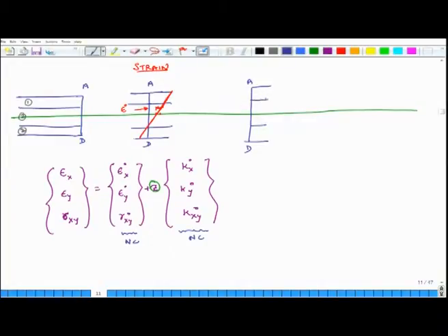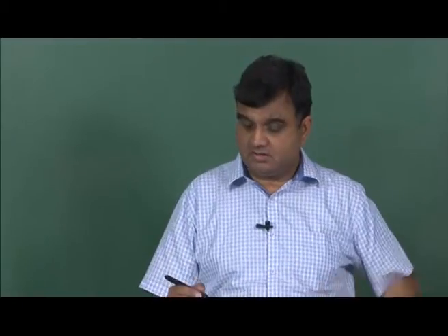And here we are going to see how the Q matrix varies, and we will just consider one single element, Q11 bar or something. The orientation in layer 1 can be some theta, and then in layer 2 it can be some other theta. So, the change in angle is not gradual, it is sudden.